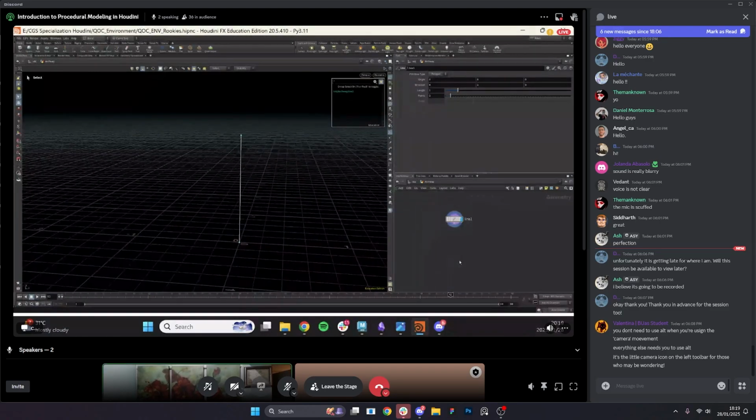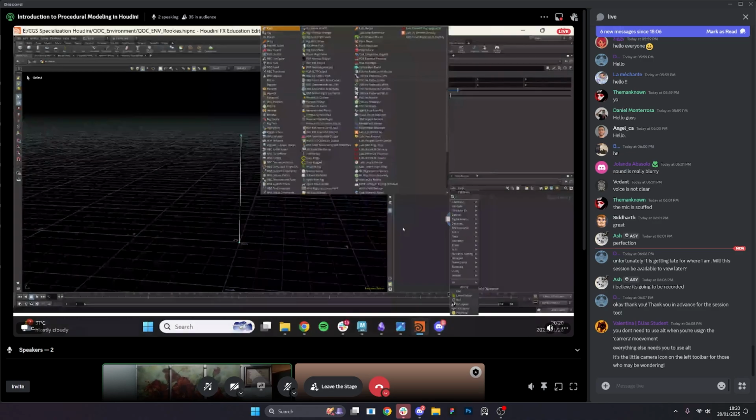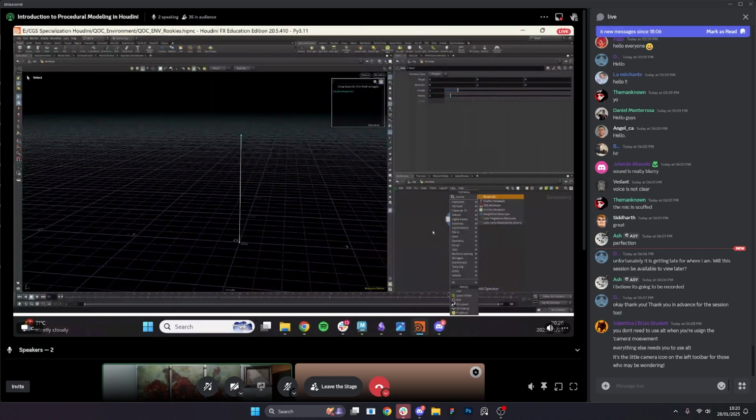Now, to get an archway, we need a few things. Firstly, we need normals, because lines, unfortunately, do not come with normals by default. So we need a normal direction, but we also need curve view. Now, curve view is a bit difficult to explain, but I'd say it's a bit like using a mask in Substance Painter. Basically, it's just a way of knowing what's top and what's bottom. In very simple terms, but yeah, make of that what you will. So let's start with the curve view. For that, we're going to need a resample node.